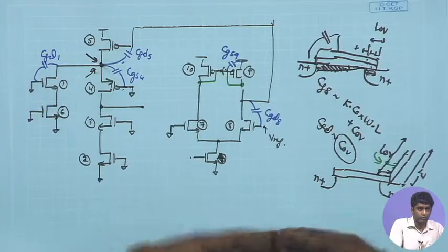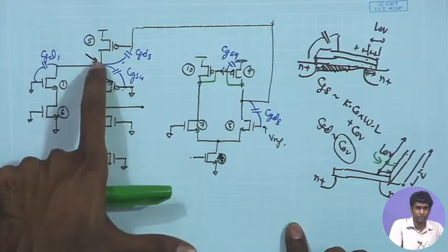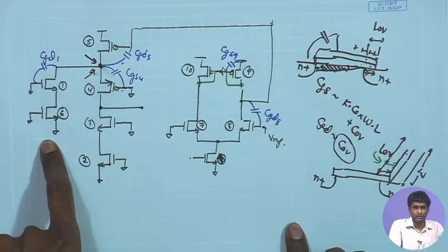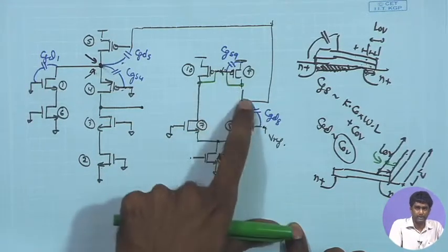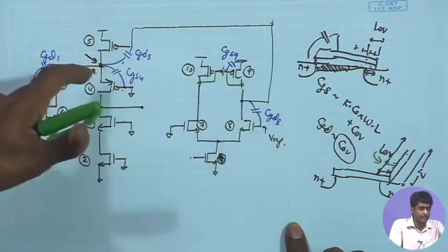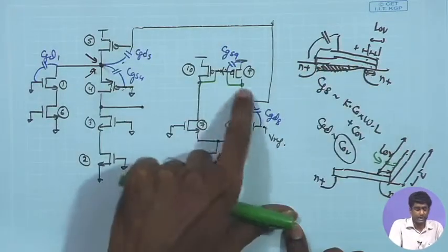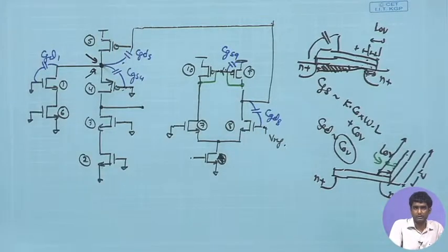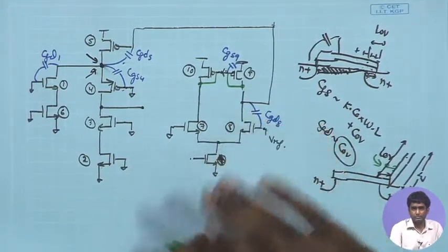If you want to have a good dominant pole compensation, the sizing constraint of this transistor must be taken care of. You should not make this capacitance too large, otherwise it will require a much larger cap over here. And the second thing that I discussed is that you should not end up making this one the non-dominant pole. This pole should not end up being lower than this one, otherwise you will have to compensate this one also separately by putting an even larger cap over here. So, any other issue?